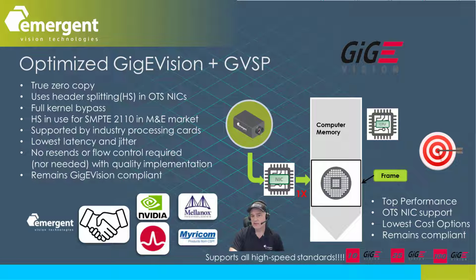It is worth noting at 25 gigabit per second and higher that the familiar PoE or Power over Ethernet is dead. Thus, new deployments should be focused on SFP technologies and distributed power systems. It is also noteworthy, even at 10 GigE speeds, that the big NIC providers do not support PoE, which forces camera vendors to sell their proprietary card solutions.